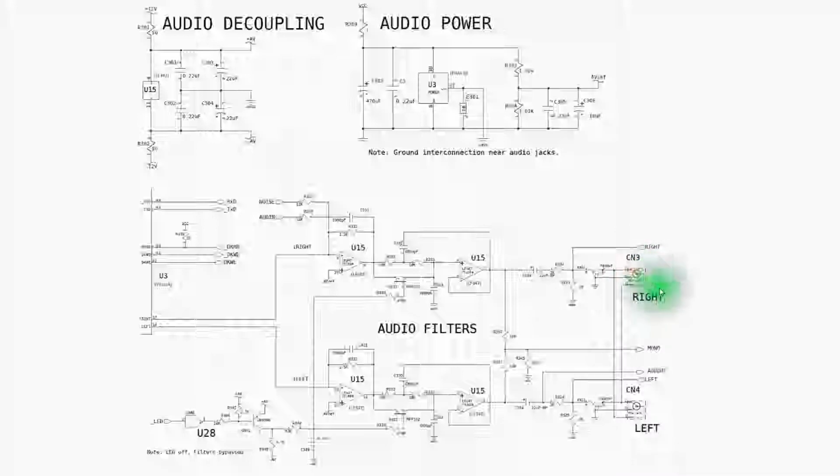to the output. So an interesting note here on these audio output jacks is you'll notice there's 3 pins, 1, 2, and 3. And what happens here is if I plug a speaker into only the right channel jack, because this contact inside of the left channel jack is closed, the left channel audio gets fed up through this bridge line. Am I tracing that correctly? Actually, I'm drawing this wrong. Gets fed up through this audio bridge line to the right channel audio and essentially mixes right and left channels.